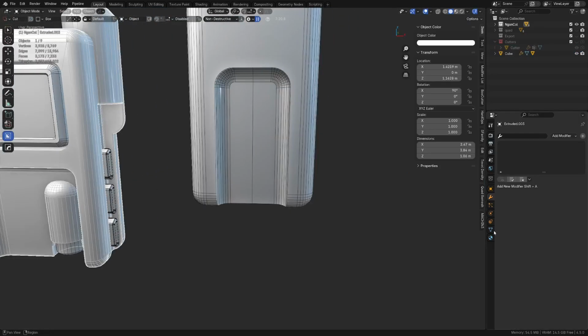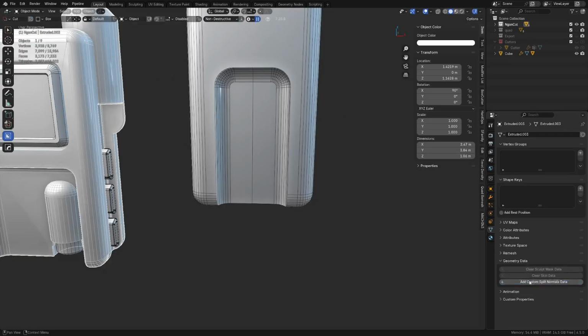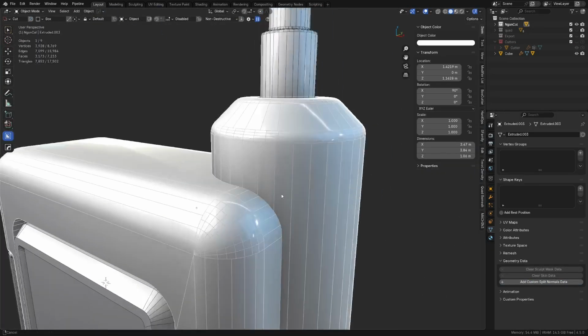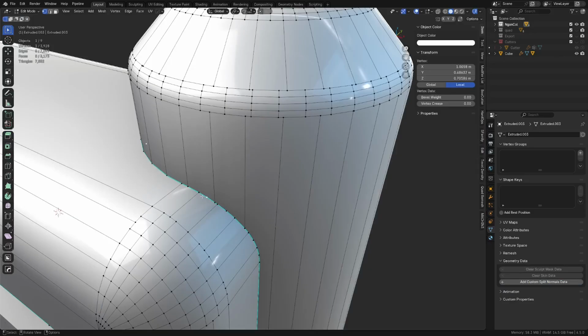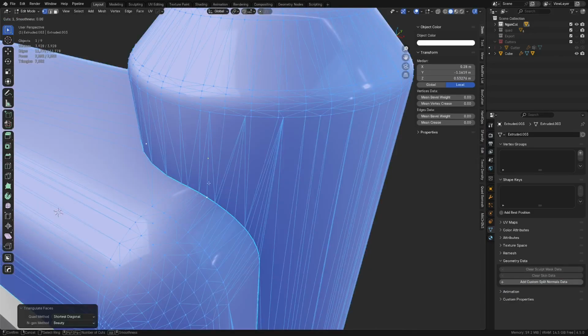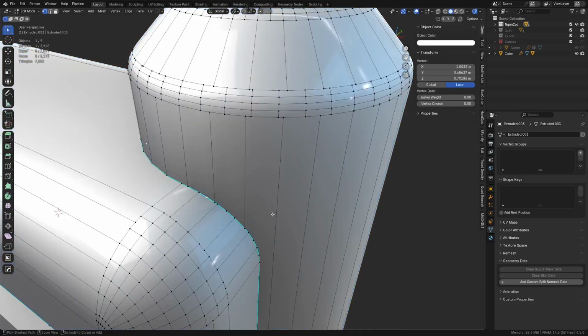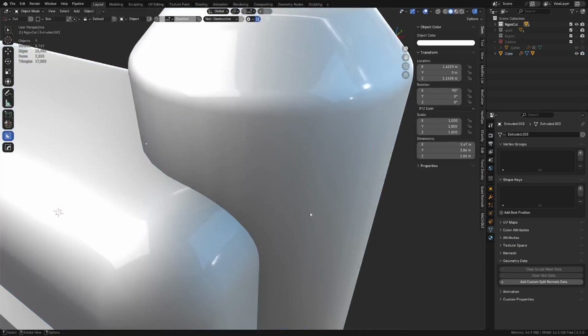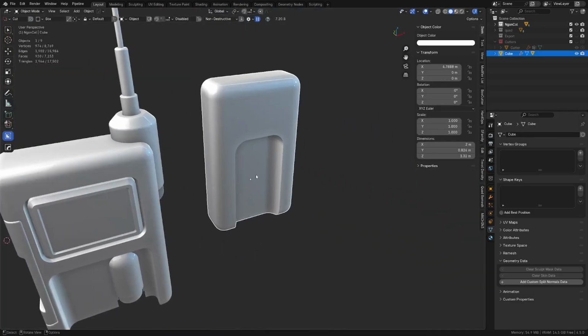And it comes in with custom normals. So if you look, clear custom normals, these edges don't line up with each other quite right. This is going to create a lot of triangulation in these areas where the shading will go to heck. Custom normals fixes that issue, but once you start modifying this mesh, you lose your custom normals a lot of times. You got to restart them over kind of.